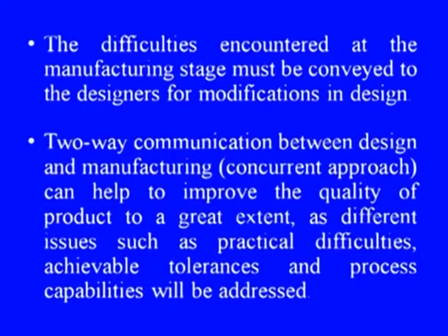Two-way communication between design and manufacturing, which is also called concurrent approach, can help to improve the quality of the product to a great extent, as different issues such as practical difficulties, achievable tolerances and process capabilities will be addressed.